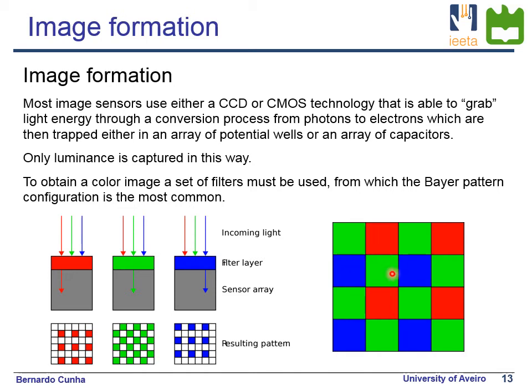And this is one of the reasons why the chrominance information typically is gathered together. Out of these 4 pixels, you create a U and a V component, and you send a single U and V component for these 4 pixels, reducing therefore the spatial resolution for color.